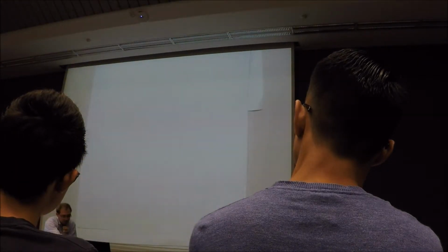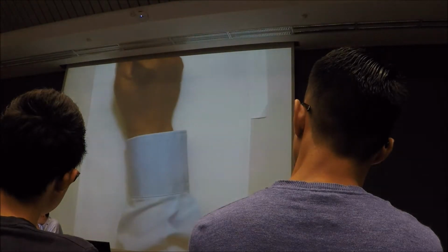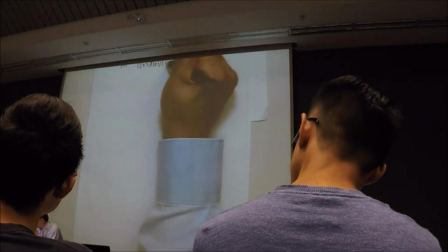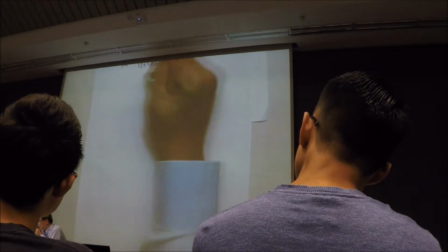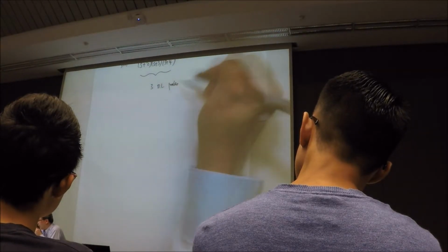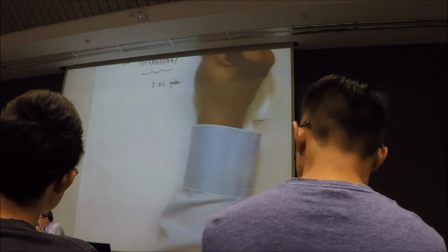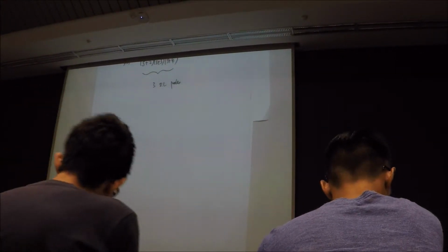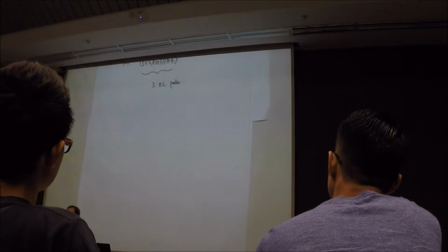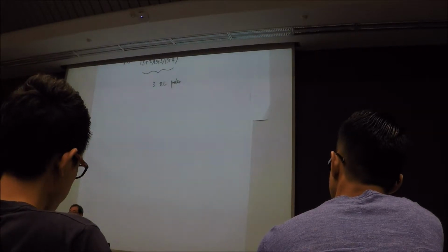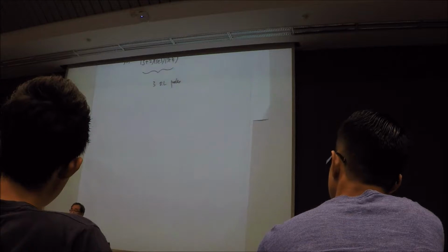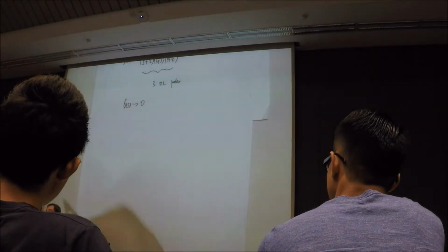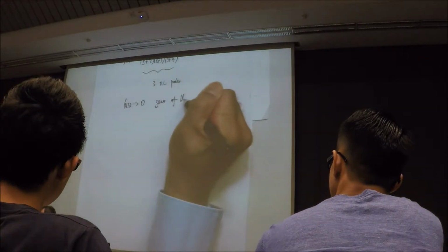That means if you have a transfer function like this, s plus 1 over s plus 2, s plus 3, s plus 4, based on the zero definition, in this case I have 3 open loop poles, but I only have 1 open loop finite zero. We mentioned how to work out the finite zero. What about the rest of the zeros? The rest are what we call infinite zeros. What is the zero definition? The definition for a zero is the point that is going to make your transfer function G(s) go to zero. That particular point is going to be your zero of the transfer function.